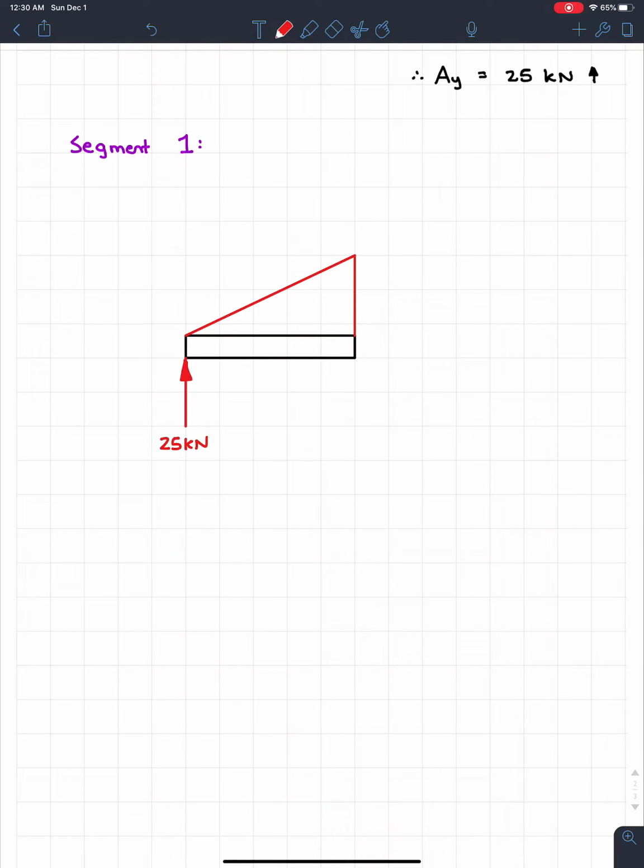And then as for internal forces, because we cut the beam, we have to replace our cut with 3 internal forces. The first one is going to be shear going downwards. Again, this will always go downwards. We have a moment, which in this case will be counterclockwise. And then we have an internal axial force, which will be pointing away from the beam. Oh, I guess this would be labeled N. So this is what we would typically do before, and we'd solve for M, N, and V for that single point.